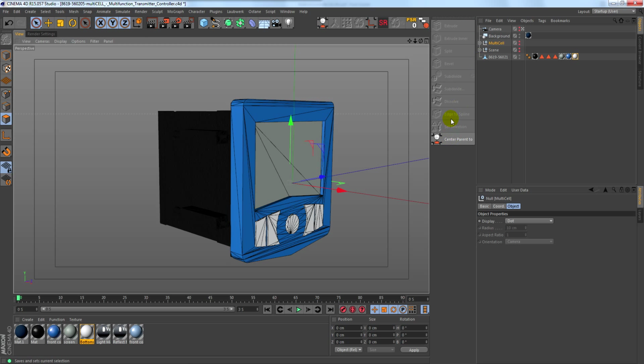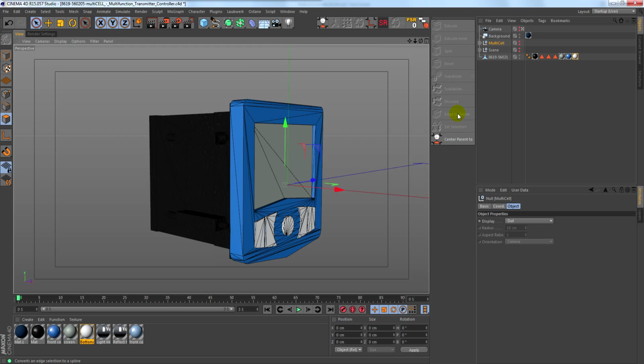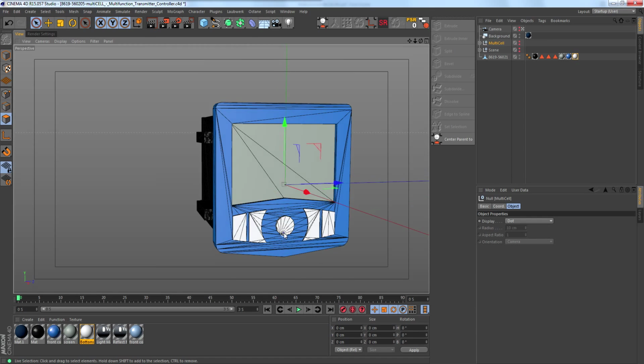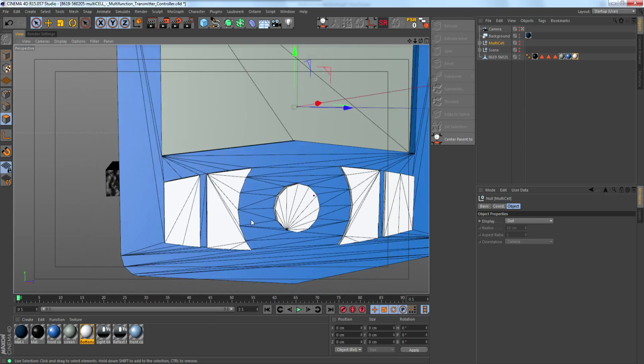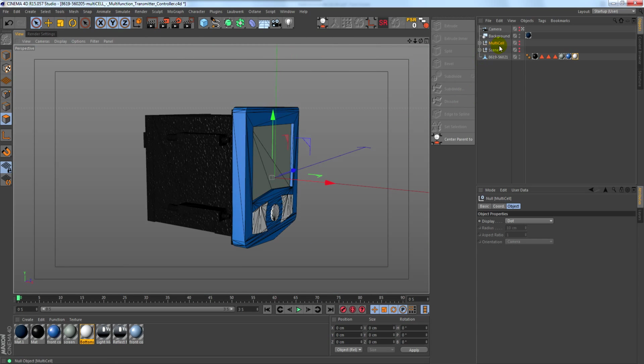I'm going to use this one technique, which is edge to spline, and remodel from there. But you can't do that with every CAD file. But you'll certainly use it at least once within every CAD file. I know I certainly do. It's real nice to take shapes like this, take the spline, convert it, and just redo everything from there. So I'm going to show you that process.